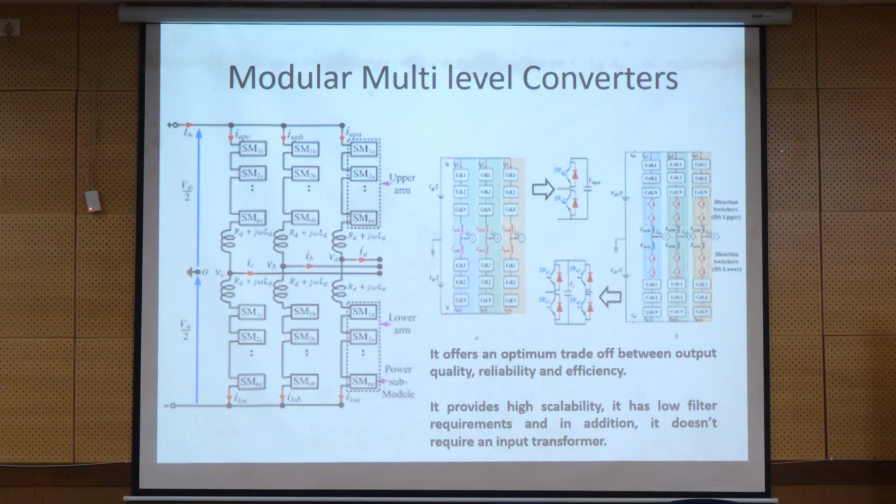VDC by 2, VDC by 2, these are the virtual DC link capacitors. These DC link capacitors are equal in magnitude, that is C1 equal to C2. These are virtual voltages, I mean to say that C1 equals C2 all the time when you are working with this kind of topology. It can be these submodules, where we have a half bridge inverter or a full bridge inverter module cascaded.